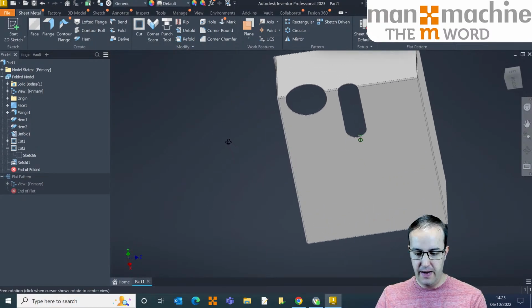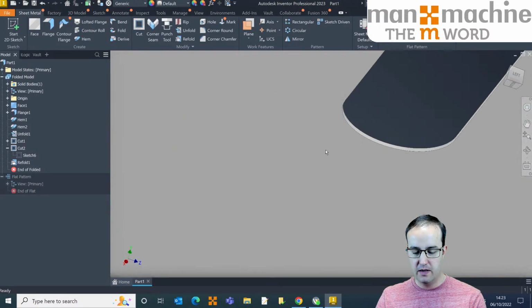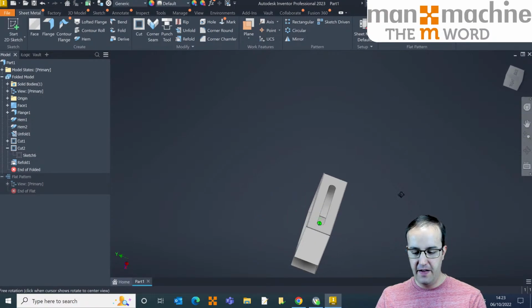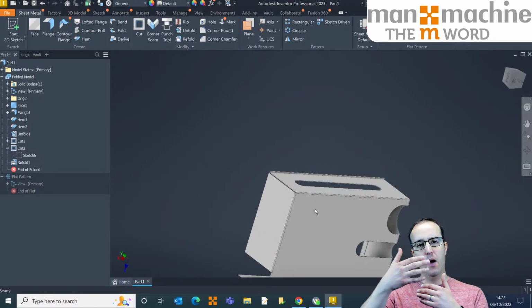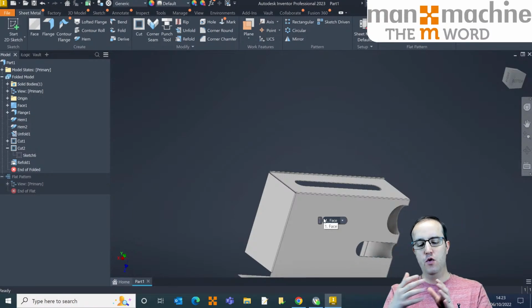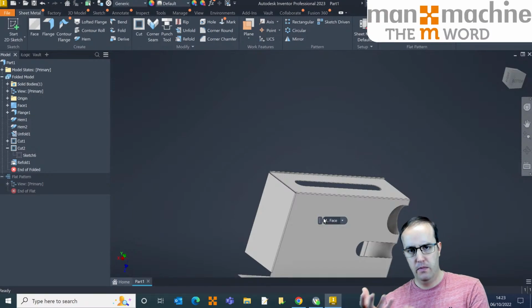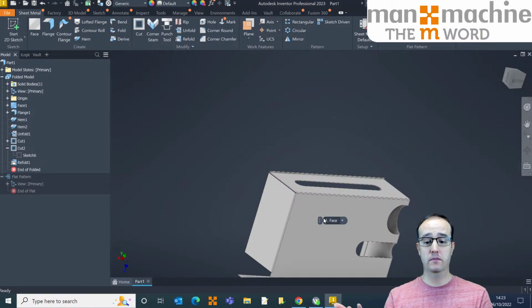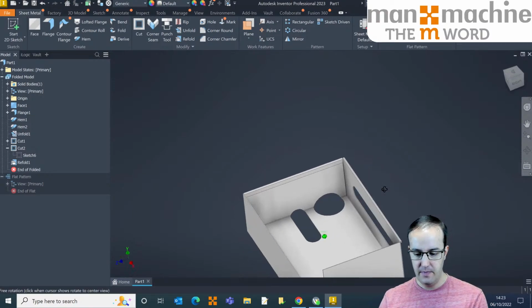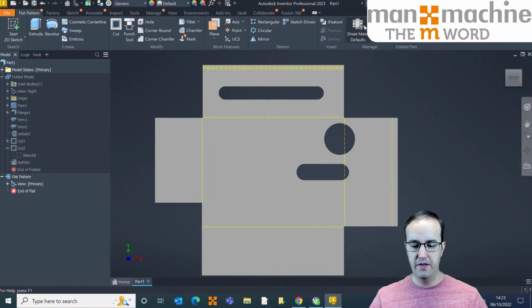What you'll find is you get a very expected result with regards to that cut. If I'd have done the same thing in 3D, I'd have had to create a work plane, looking at that, then create a circular cut all the way through, and you wouldn't have got the same shape because it will be treating it like you're cutting it when it's folded. And again, there's workflows to support both, do it when it's folded, or punched when it's flat or cut when it's flat. Do it in an unfolded state. Again, as you'd expect, your flat pattern will update to show you those components as necessary.